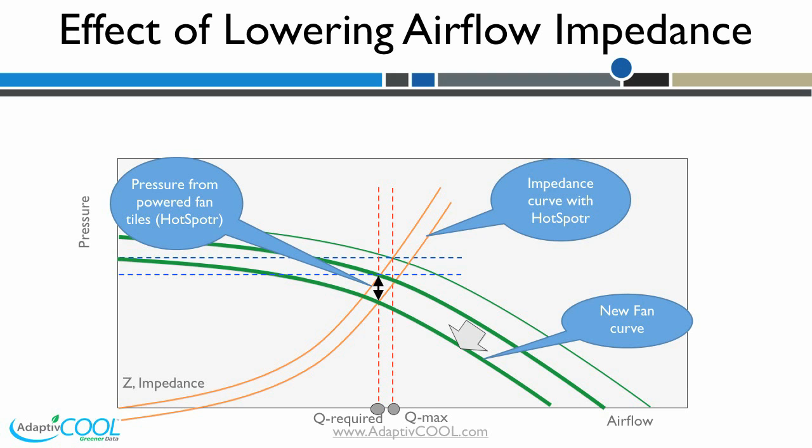Usually, airflow in a data center is controlled around the hottest points. If airflow at these hot spots can be controlled to manage temperature, airflow at the rest of the room can be lowered and significant energy savings can be obtained.